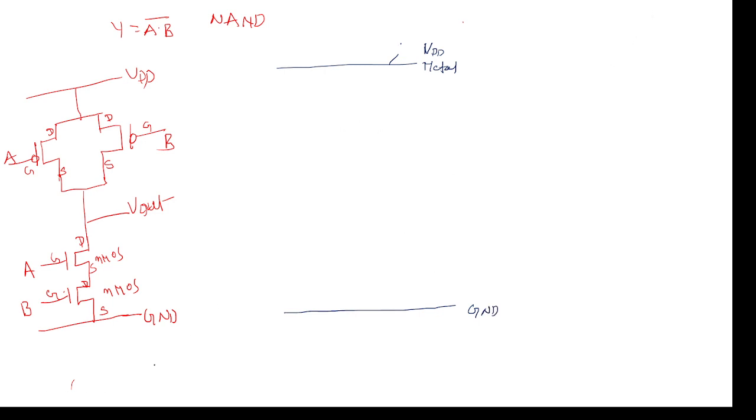We know that the transistor symbols are: PMOS transistors are poly or yellow over red. This is the original symbol, poly over red. So I am taking two transistors at a time, so I am drawing two transistors. That is the reason I am taking a long wire. So this is the P diffusion. This is the original symbol, poly over red; or else red is horizontal and yellow is vertical. Both ways you can use, no problem, both are correct.